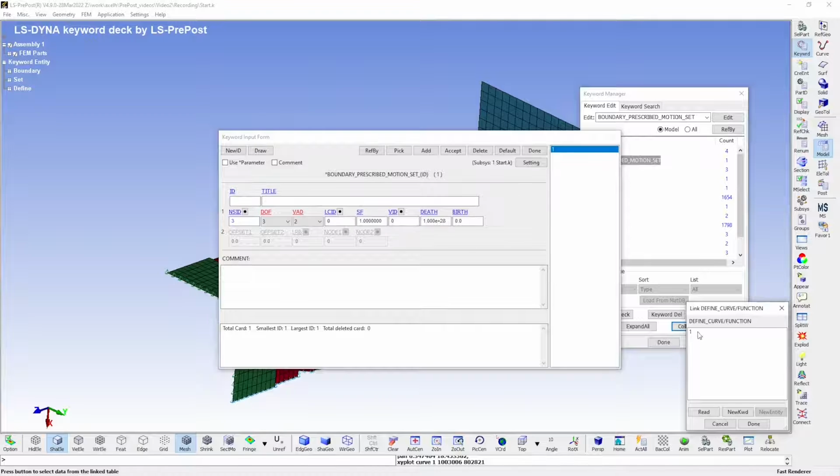Select it here. As you could see, I defined the curve so that it reached an ordinate value of 1. It is up to you to decide if you want to normalize your curves in this way, or if you prefer to create them with the actual values directly. But I find it is easier to work with the normalized curves and use scale factors. So you can then use the same curve definition for several things. And it is also much quicker to just change a scale factor later if you want to have a different value.